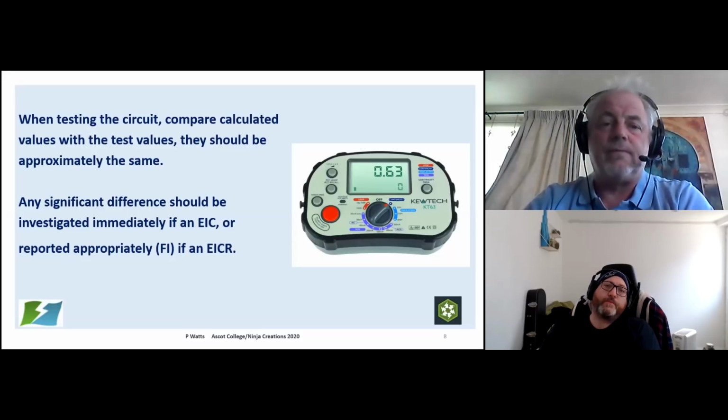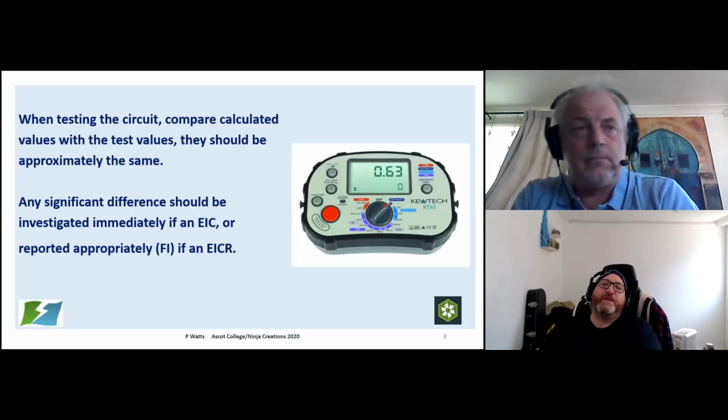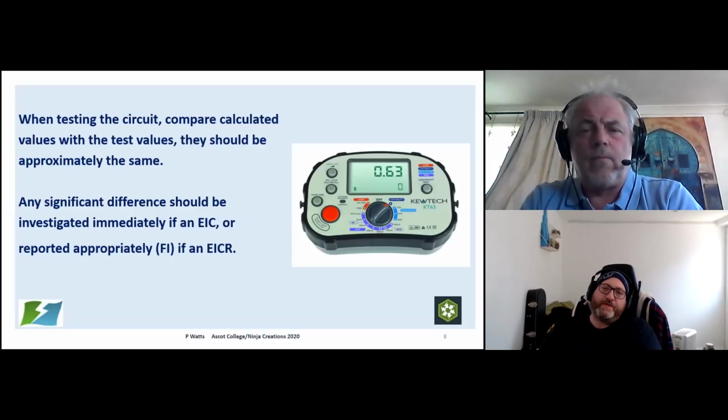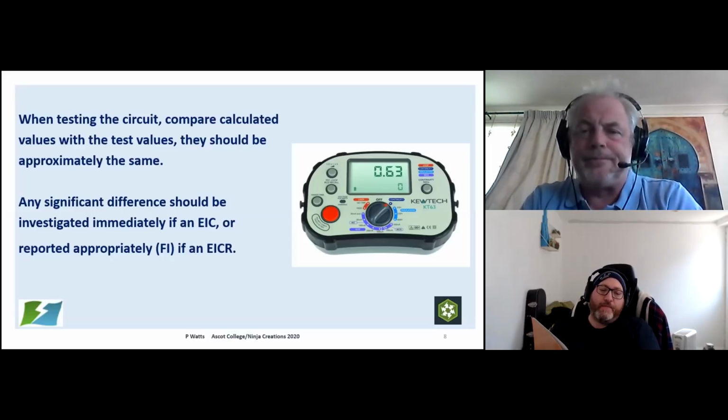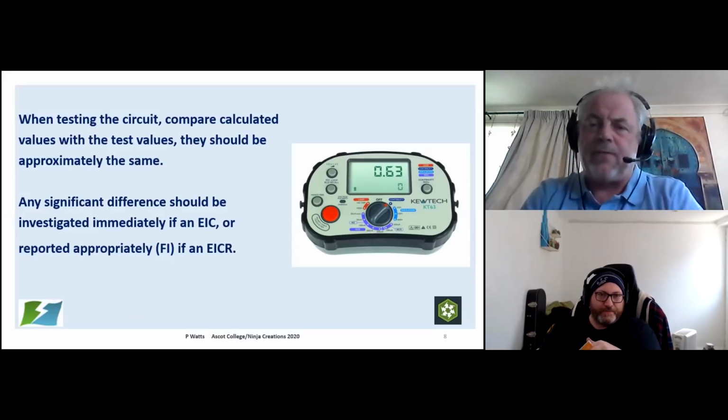Further investigation. Before we leave this area, Duncan has said, if it's a 20 CPC cable, do we use the multiplier of 1.2 to the cables? I believe he's coming from table B3, these multipliers here. Not yet. If it's incorporated or bunched in the cable. Not yet. We'll cover table B3 towards the end.